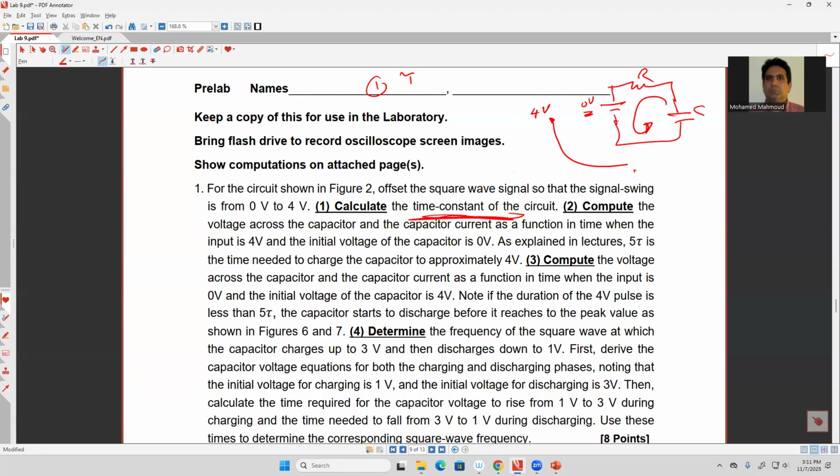Okay. Number two, you need to find the initial voltage, and in this case, the initial voltage is 4 volts. Number three, you need to know the supply. Here the supply voltage is 0 volts. So using the three values, you can easily calculate the equation during discharge.